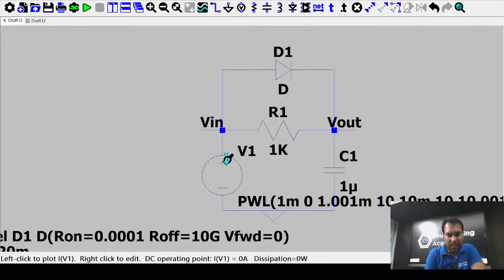So this is the way you can analyze on paper, and once you simulate it in your file, of course that simulation will give you a result. Just like a MOSFET, where you think that ID is equal to half mu n Cox W by L times (VGS minus VTH) whole square, but if you talk about the whole equation, there are a lot of effects, like 1 plus lambda VDS. So in the simulation and the analysis, I may have some fraction of difference.